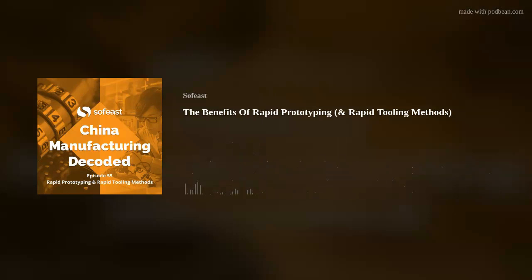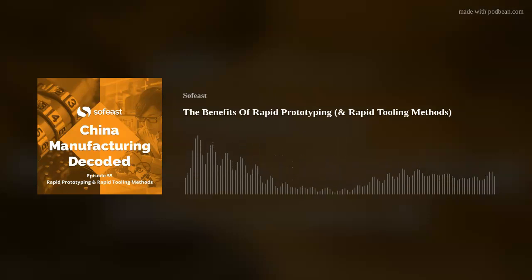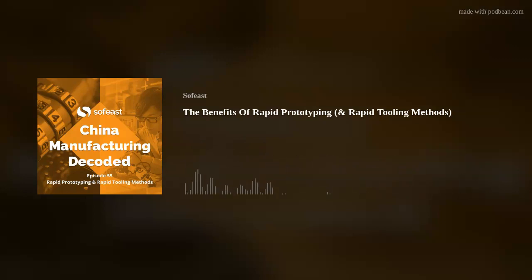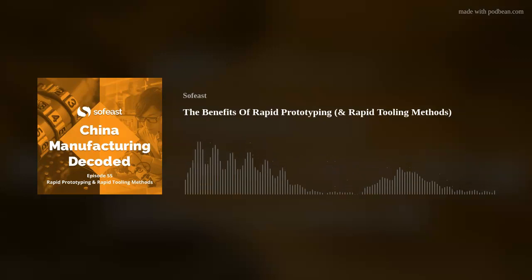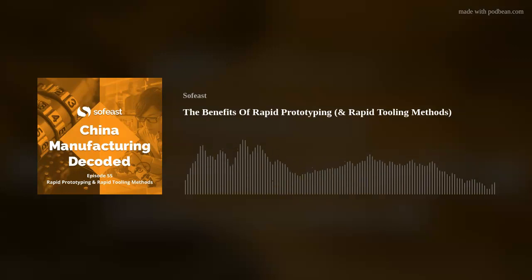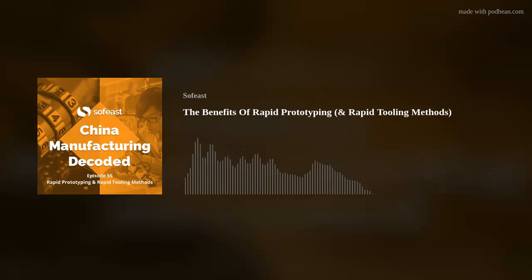With silicone rubber, you can make 5, 10, maybe 20 shots, and you can make the mold itself pretty fast. Actually, we describe how to make it on the page that you mentioned, from our website.